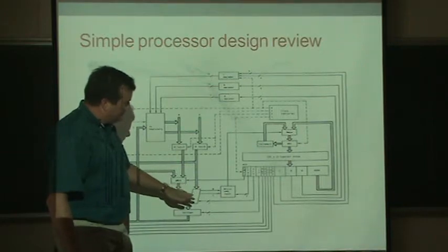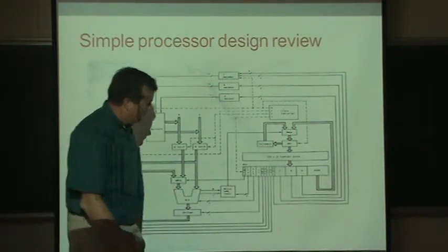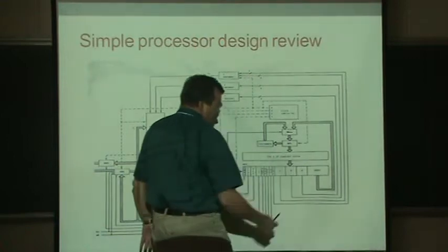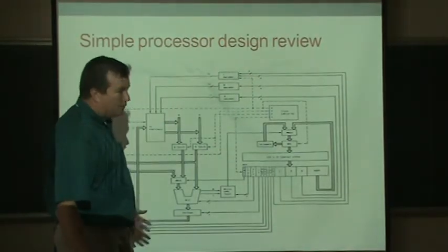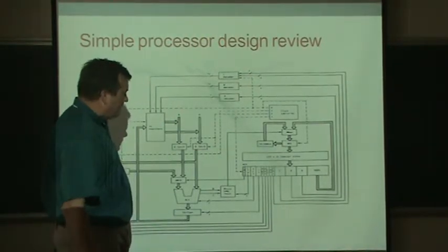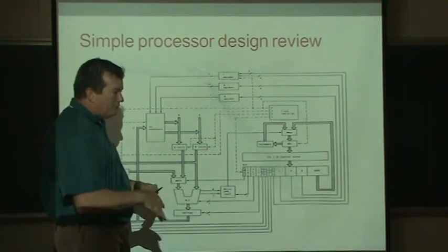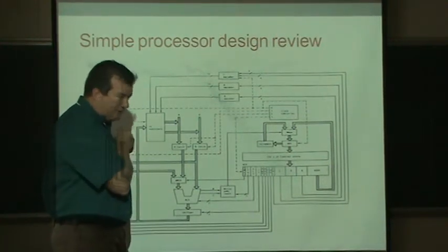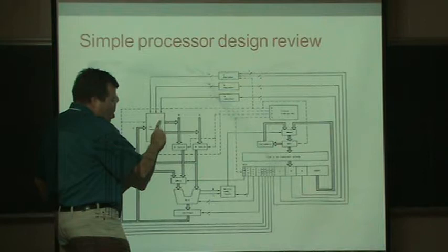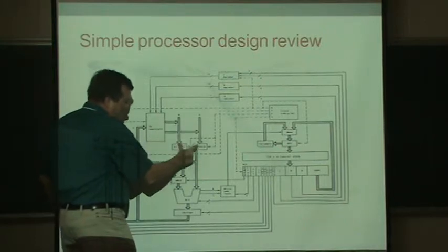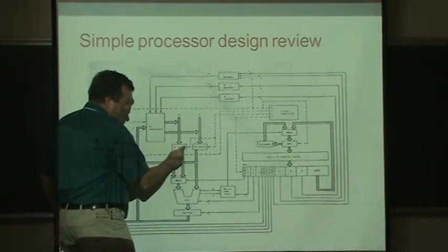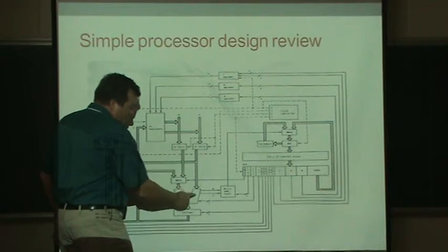the second step, which is decoding the bits of the instruction. The third step is typically in preparation of a mathematical operation. We might have to take data in some of our registers and latch them or capture their values. These are now the inputs to the ALU.